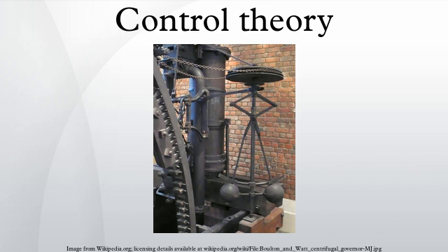The desired closed-loop dynamics is obtained by adjusting the three parameters, often iteratively by tuning, and without specific knowledge of a plant model. Stability can often be ensured using only the proportional term. The integral term permits the rejection of a step disturbance. The derivative term is used to provide damping or shaping of the response. PID controllers are the most well-established class of control systems, however, they cannot be used in several more complicated cases, especially if MIMO systems are considered.